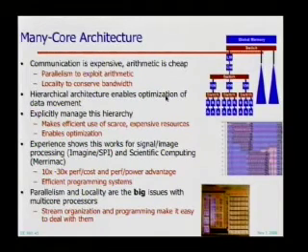That requires building a hierarchical machine. It's not sufficient to have a linear memory hierarchy. At each level of that memory hierarchy, I have to have visibility to which of many co-equal pieces of storage on the die my data is in, so I can make sure that it's co-located with the other data it needs to be operated with and with the arithmetic unit that's going to do the operation.